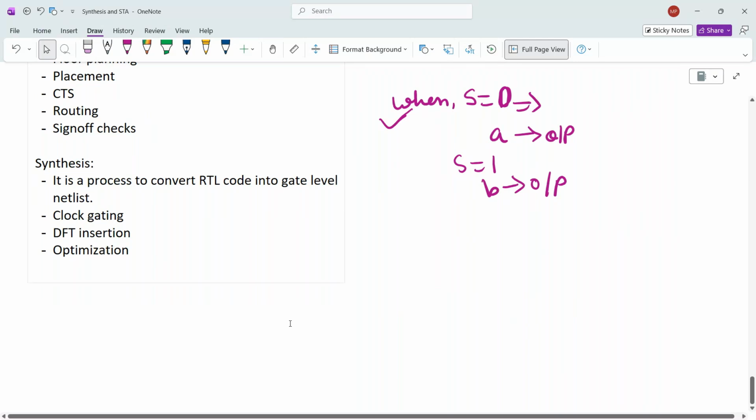Right now, what are the inputs required for synthesis? Can you tell me? Yeah, so first we'll refer the RTL code. Then we need libraries, both physical library and logical library. If you're doing the physical level, we need the physical library also. Then the tech files, and mainly these are the inputs. Yes. So I will start with the necessary inputs.